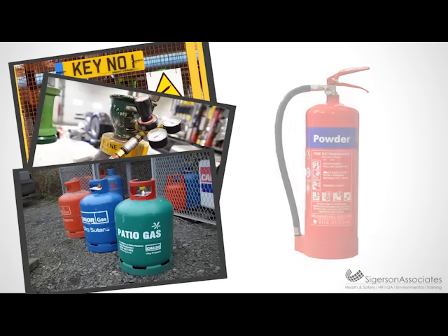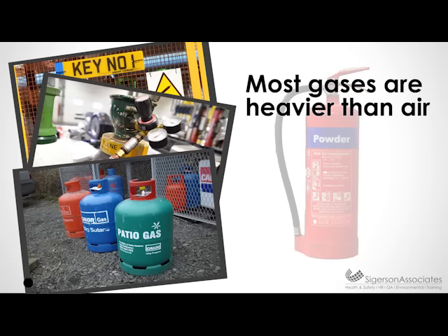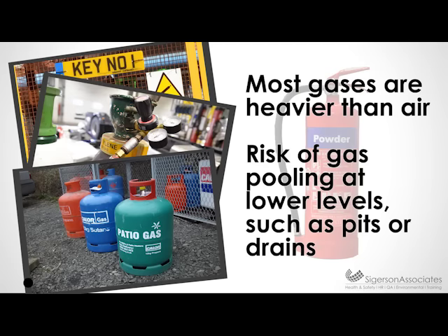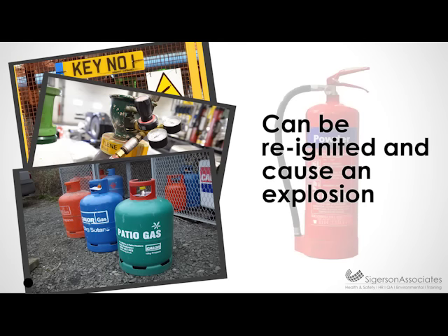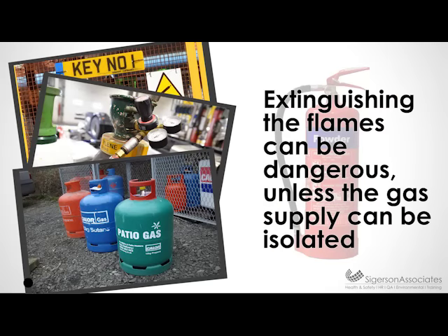However, please be aware that as most gases are heavier than air, there is a risk of gas pooling at lower levels, such as in pits and drains. This gas can then be reignited and cause an explosion. Extinguishing the flames of this type of fire could be potentially dangerous unless the gas supply can be isolated.